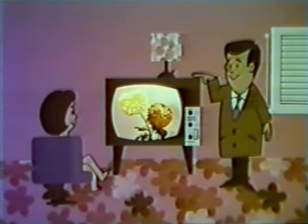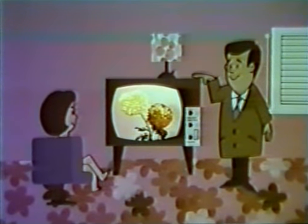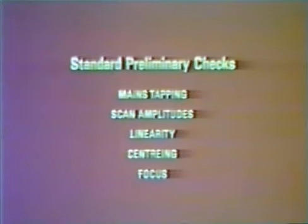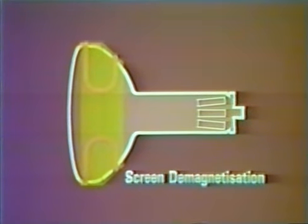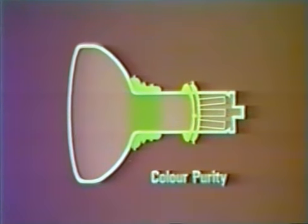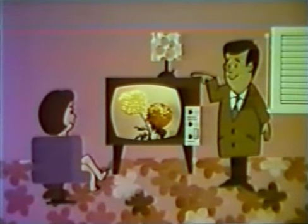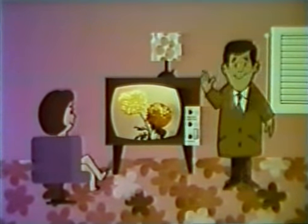To sum up, the aspects which need to be checked and occasionally adjusted when a color television receiver is installed are provision of a good signal, standard preliminary checks, screen demagnetization, color purity, convergence, reference white and grayscale, and finally, the viewers should be shown how to get the best results from their new color television receiver.